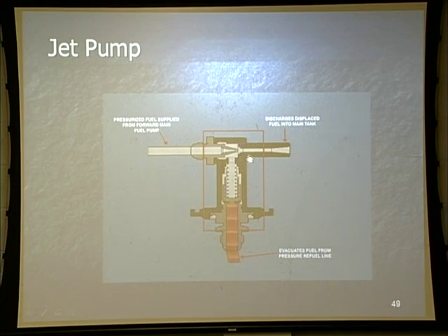It creates a suction or a Venturi. That suction is going to suck this door open with the aid of this fuel weight, evacuating the fuel out of that line and putting it right back into the main tank itself. And it's going to look just like this.